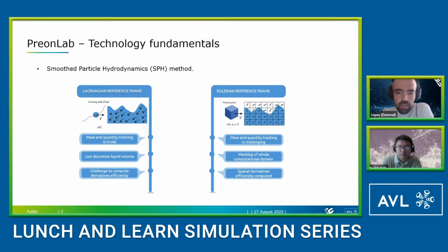And for example, in the finite volume method, these small parts of the mesh are called cells. And then what's done, we apply the governing equations of fluid flow, which are mass and momentum conservation, to each cell. And then we ensure that we get a conservation inside this cell. And in this way, we compute the variables that we want. So in the case of fluid dynamics, of course, we're talking about pressure and velocity. And this method is really efficient to compute the spatial derivatives.